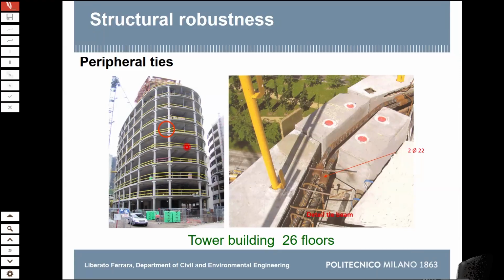So you mean what? Well, yes, it's true, but it's also true that most of the time we do not worry, but also in that case the structure changes. So if you lose a support, no matter whether it was dry or monolithic, the structure immediately changes its scheme. So if you lose the support, no matter how it was done, immediately the beam starts working in the other way. Yes, that is for sure. But you have to check that it acts as a tie separately.